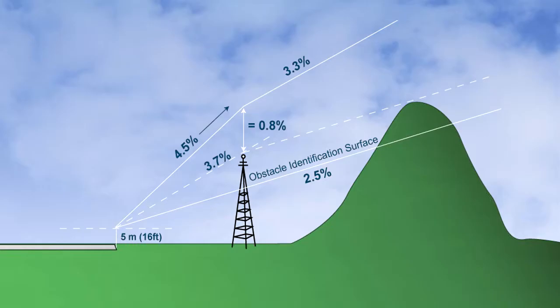The minimum obstacle clearance equals 0 at the departure end of the runway, DER, and thereafter increases by 0.8% of the horizontal distance in the direction of flight, assuming maximum divergence of 15 degrees. If the resultant PDG is too steep, a turning procedure to avoid the obstacle laterally might be the answer.